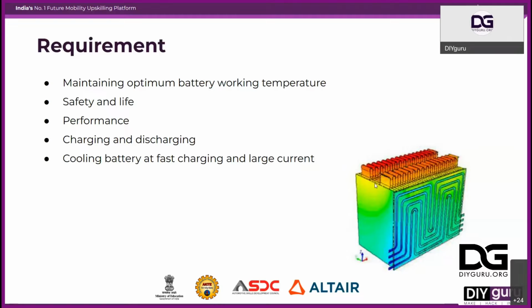So your cell will heat. So that will decrease the battery life. But if you want from that one battery pack to supply 200 ampere hour, you have to provide thermal management so that it cools down your battery. If your battery is working at a very cool temperature, there won't be an issue on your performance, on your life and everything.